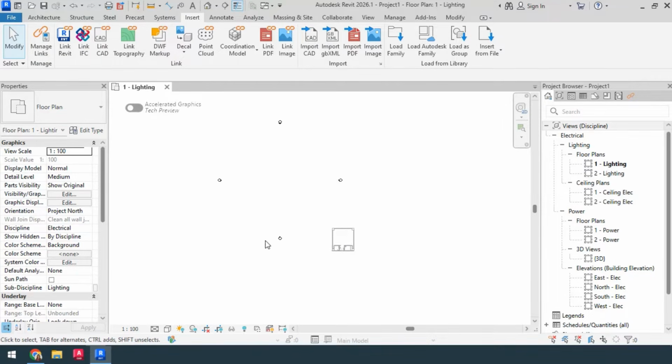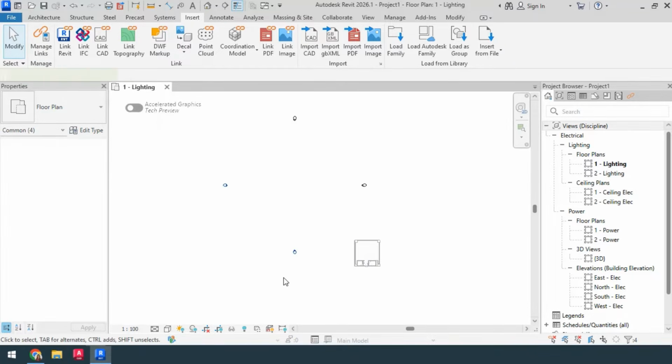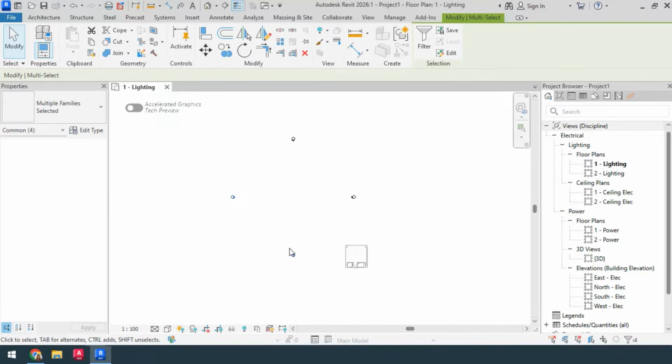These symbols you see here are the elevation markers. If for some reason the linked file's markers are outside your workspace area, you can move them. I can select them by dragging. I drag them, and these two were selected. I hold down the control key for the other two, and I can move the elevations using the keyboard arrow keys. So they're positioned around the modeling space.